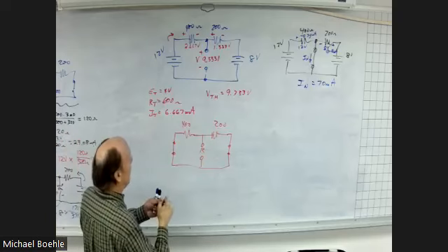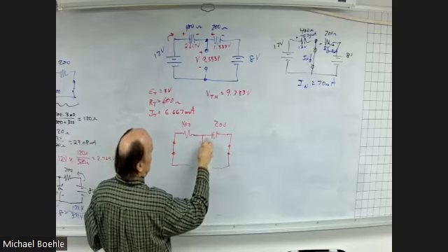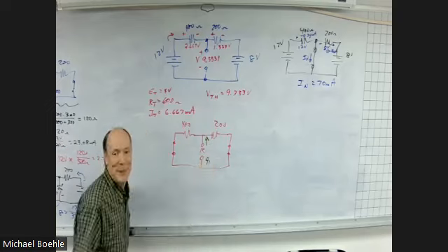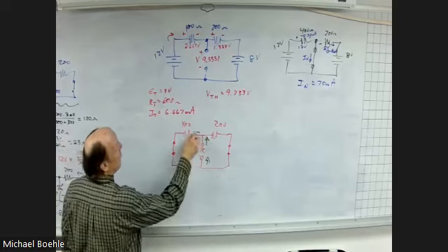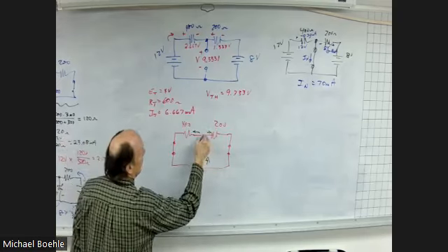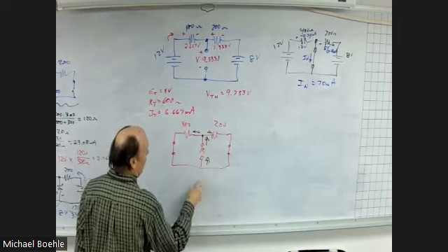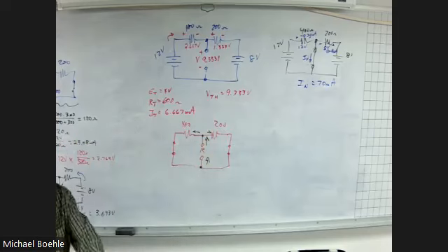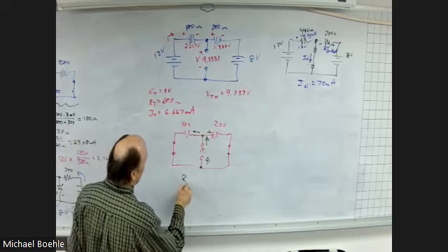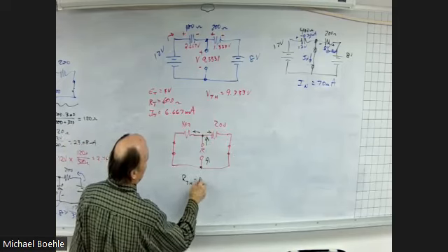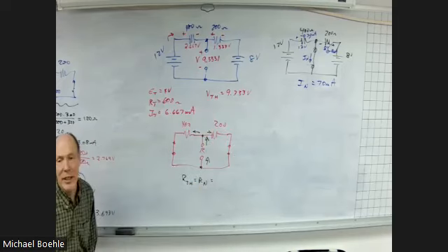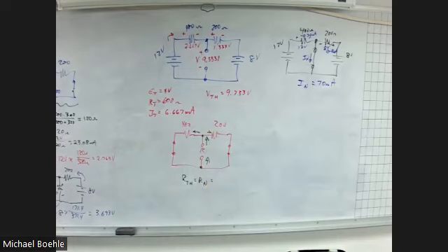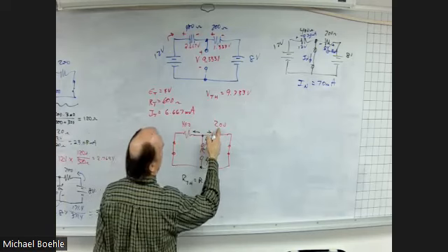Because I'm basically saying come in here and get back to there. So when I come in there, I have 2 paths. Because of the shorts, they're both connected to that point. Boom, parallel. So my Norton and my Thevenin resistance use the same method to calculate the resistance. That's why they're always the same.